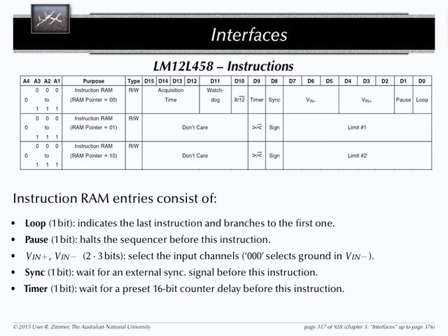You can tell your AD converter to prepare yourself for a 12-bit conversion between these two input lines and wait for the trigger from the outside. The trigger comes from the outside, do your conversion, store it someplace. And you can explicitly program a timer so that you say, from now on, wait so and so many cycles and then convert. Okay.